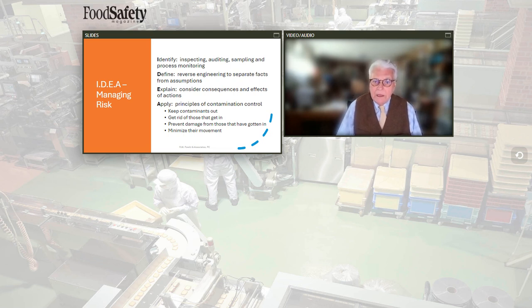I've been in enough plants where the plant itself has gotten into trouble with the overuse of disinfectants, where, being flushed down the drain, it has toxed out the local sewage disposal plant or the plant on site and basically killed off the entire biome of the plant.